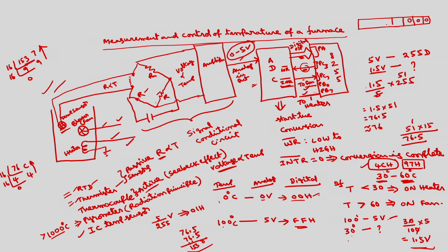This is port C upper, which we are going to take as an input port, so 1. This is port A, which we are using as an input port, 1, and the mode selection for port A, I am taking 0, mode 0. And this is for I/O mode, this is 1. So, it will be control word 98H.